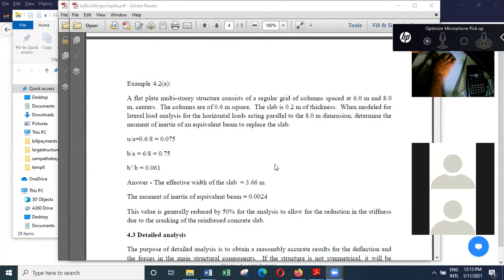And when there is a movement in the building, you will get some accelerations associated with it. So you have to actually control those accelerations, and that's what we are going to look at after the lunch break. Do you have any questions on these minor things that we discussed now, like representing the wall as a column, how to use the rigid arms to represent the actual dimension of the wall, and also the importance of considering only the important effects when you are doing the modeling?